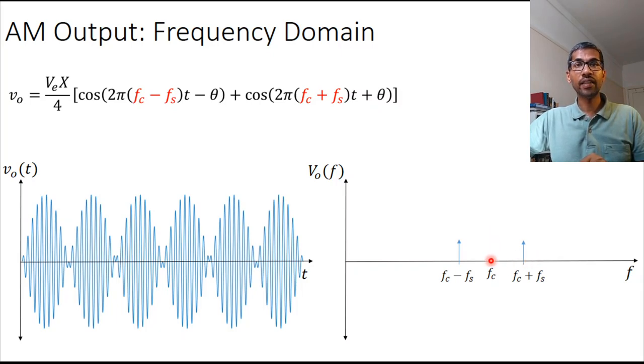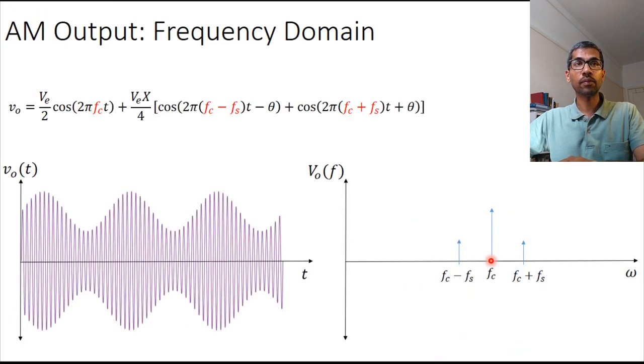In the previous case, when we looked at this, the carrier is not suppressed, so we say carrier transmitted. So double sideband, carrier transmitted amplitude modulation. One of the reasons why you use the terms transmission and suppression is because amplitude modulation is also used in communications.